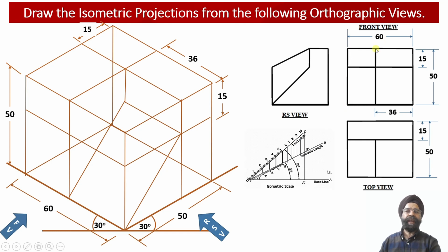How do we identify it has got two segments? Because there is a solid or object line which is going to divide this portion of the vertical web, which is going to lie onto the left hand side of the solid. So now we can check at a depth of 15 millimeter from the top face, we have obtained an inclined surface over here.